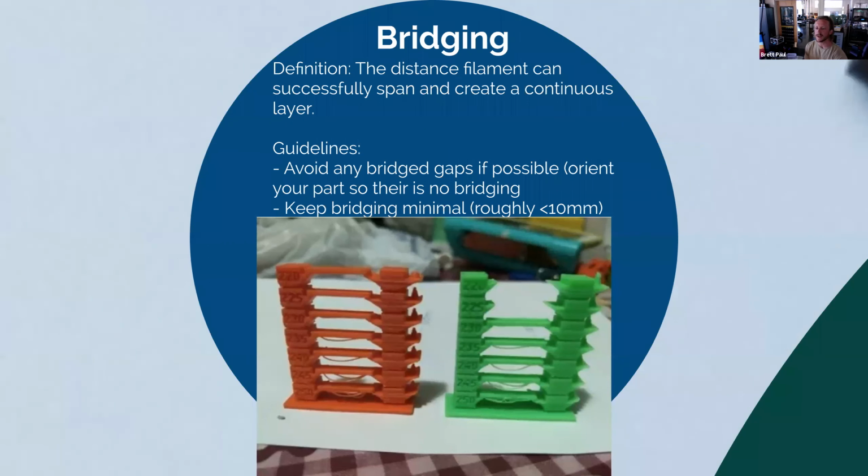You can do support structure, but anything that requires support structure is going to have a, let's say, not as good surface finish. If that's hidden or if that's acceptable within the function of the part, then we can apply support structure. And I use support structure all the time. So it's not a rule that you can't go less than 45, but it's something to be aware of as you're designing. I gotcha.